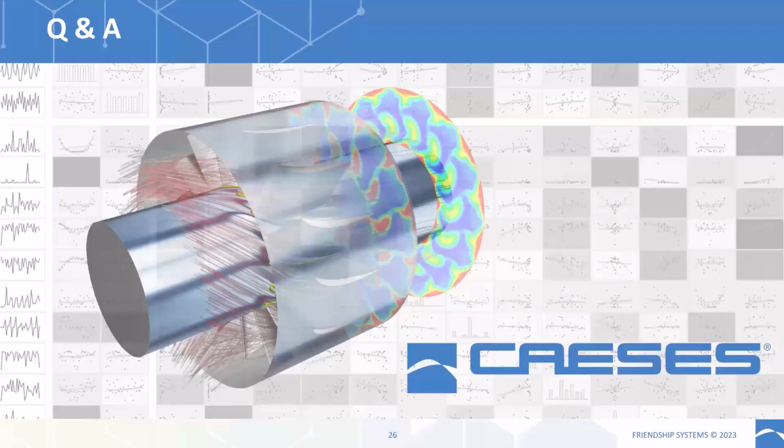So I think it's important to note here that, yes, in these demonstrations, to speed up the whole demonstration and not overcomplicate things, Carsten and Hedi have used a lot of predefined definitions. So for example, for meridional contours, for 2D airfoil and so on. So at every one of these points in the process, we provide, so to say, a library of predefined definitions. But first of all, you can modify these definitions because they will just create a bunch of objects like a curve with points and design variables.